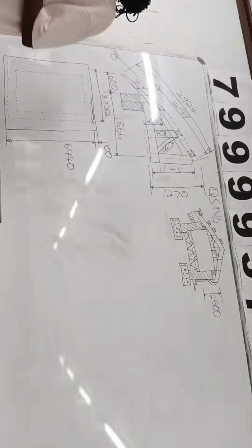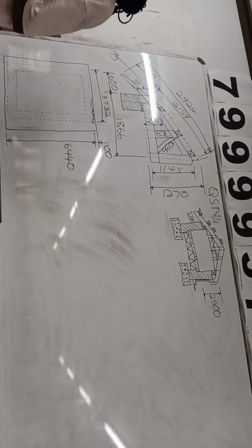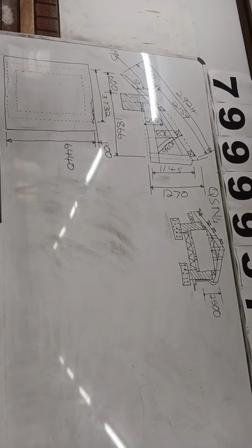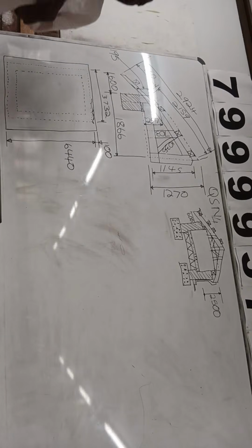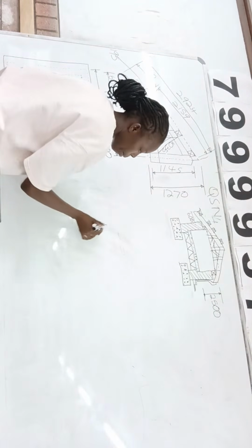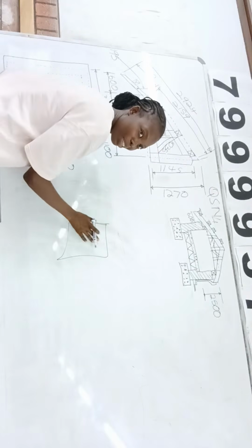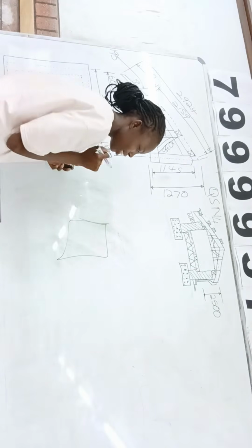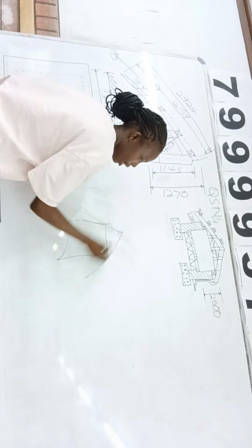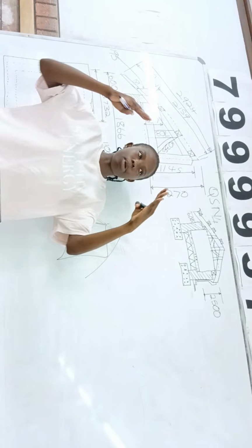Okay, and then fiber cement roof sheet roof covering, fiber cement ridge piece, 15 by 200 fiber cement fascia board. So, fascia board, I'm not good with 3D drawings, but this is our roof, and on this part I get a gable roof, a triangle like this.